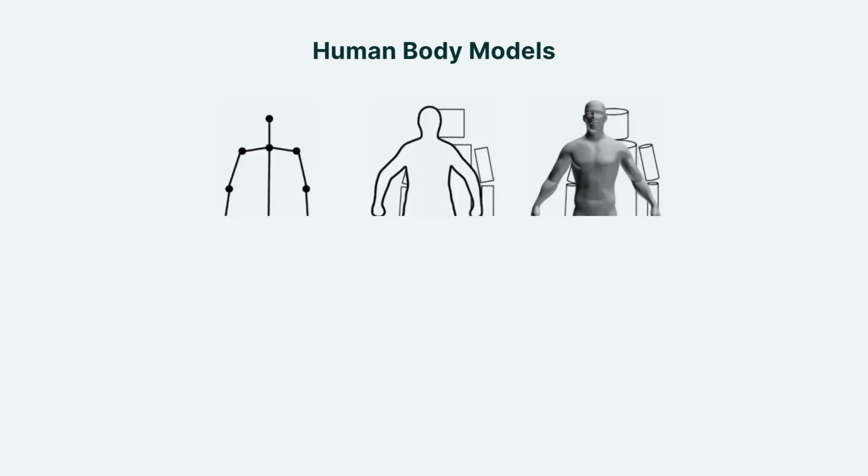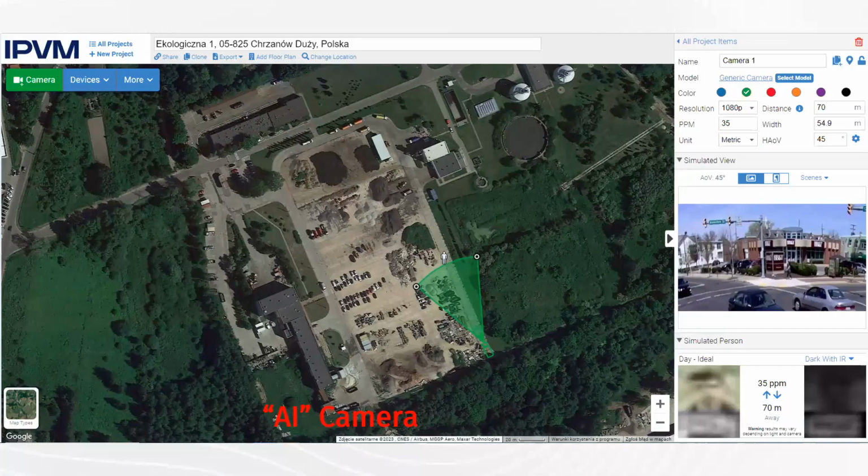But still, those cameras can detect a person from farther than the smart motion detection. Those professional cameras can detect using around 35 pixels per meter. Some manufacturers say 40 pixels, some say 30 pixels, maybe in a perfect scenario. Overall, this means that compared to the smart motion detection camera, this one can see around 50% further, because the distance is 70 meters instead of 49.